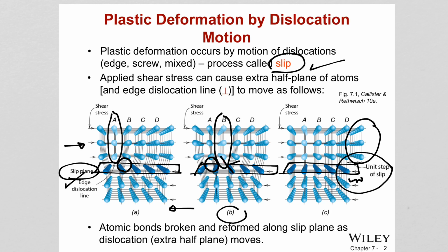So when we reached the yield strength, plastic deformation was happening, right? That means when you reach the yield strength, the shear stresses generated inside the material reach a certain volume that is capable of making dislocations move inside the material, basically.